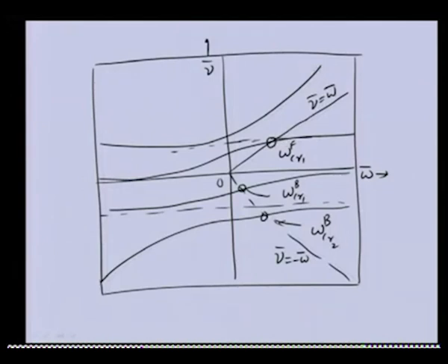And if we see the frequencies, these are the frequency lines, and at a particular omega, that means if we draw a vertical line at any position, we are getting 4 intercepts to these frequencies. This is because we had a 4-degree polynomial. If we draw an identical line at negative omega, we will get 4 intercepts again, and they will be the same as on this side, because if we rotate the rotor clockwise or anti-clockwise, we should get the same whirl frequency.